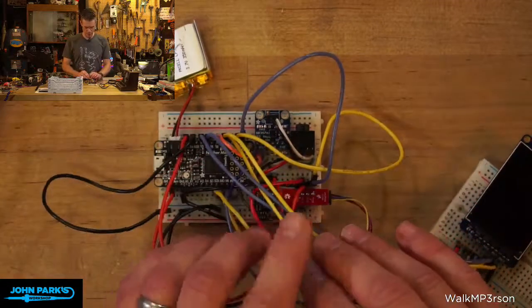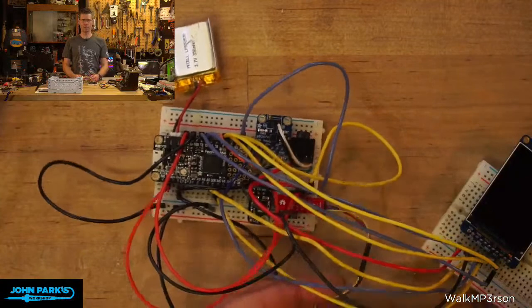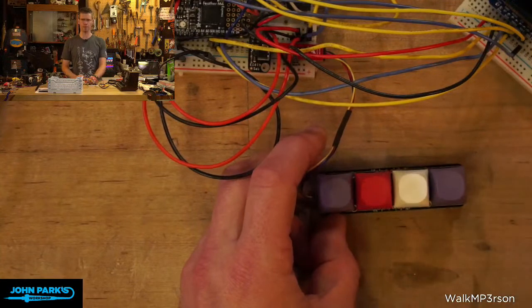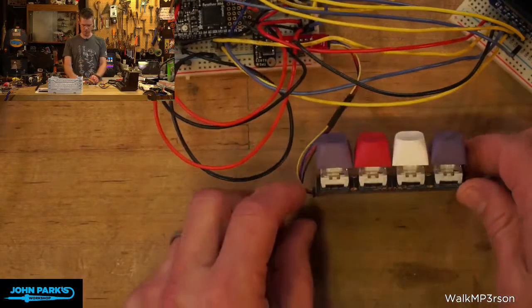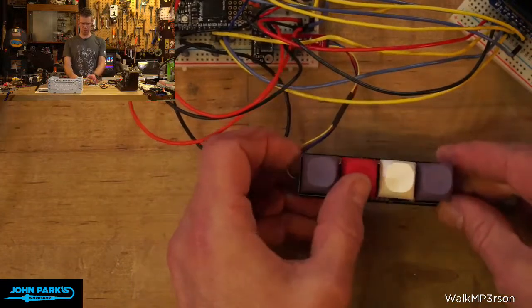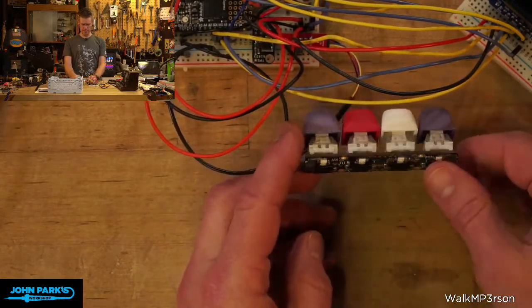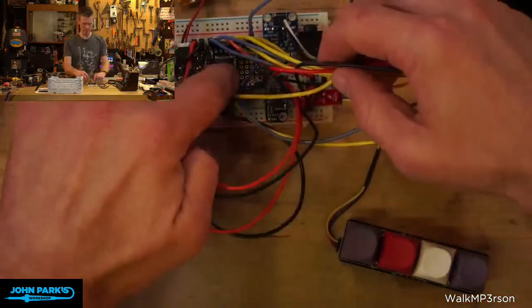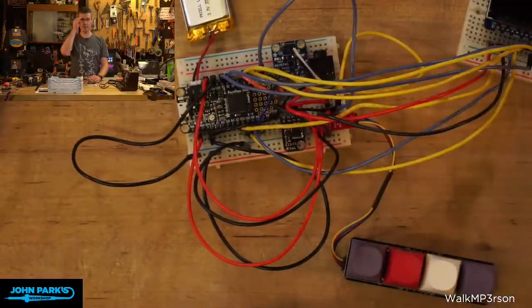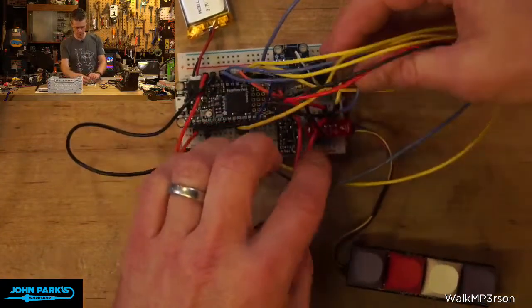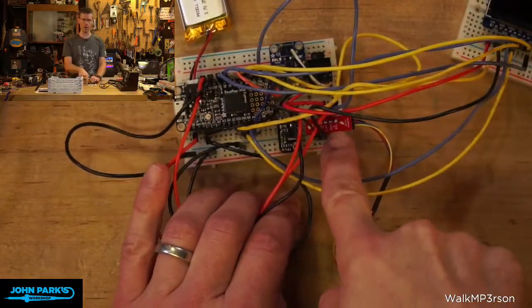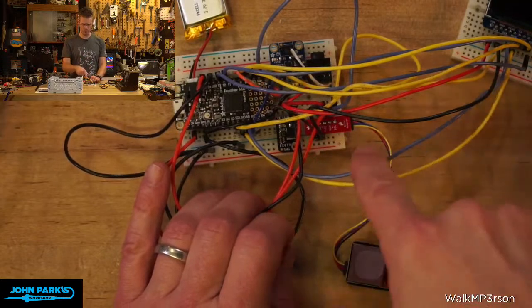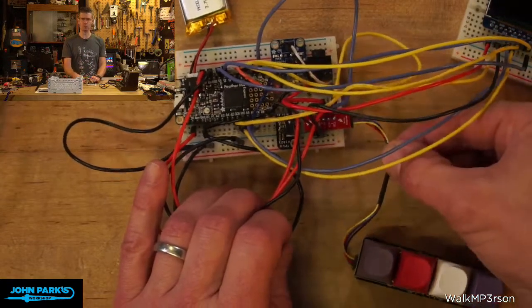And then the other connections I have are, I'm running a set of transport controls. So next song, previous song, play, and stop. And maybe I'll adjust what those do, but this is just a nice set of Neo key mechanical key switches. I got some clicky Kailh box whites, and that is running over I2C. And so for I2C, since my Feather M4 board here does not have a Stemma QT/Qwiic port, I'm using one of these great little SparkFun breakouts that has 4 header pins that go into your breadboard or your perf board or your circuit board, and gives you 2 of these Stemma QT cables.